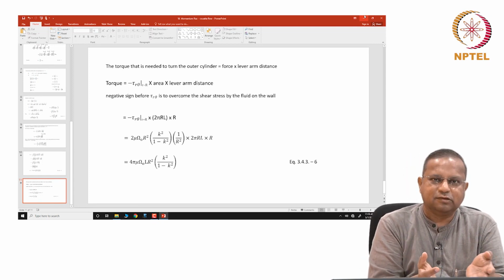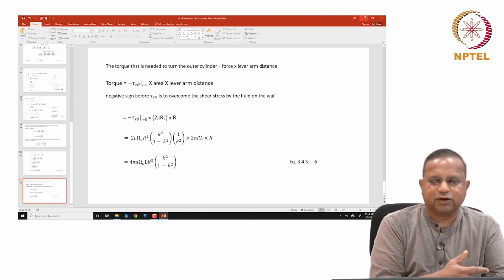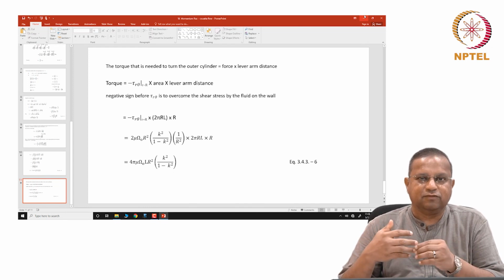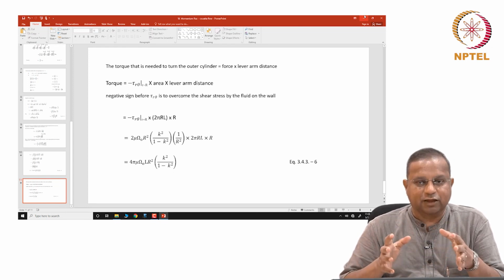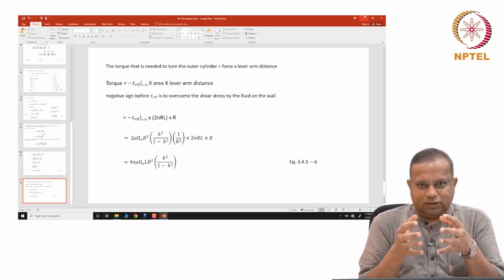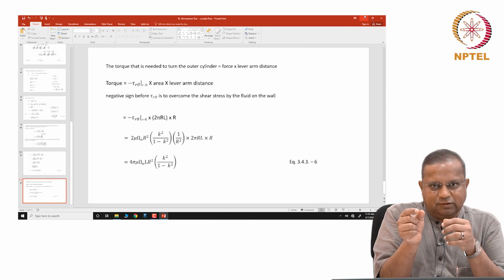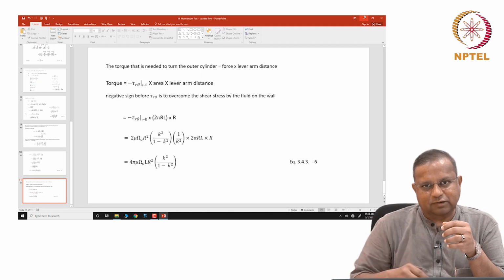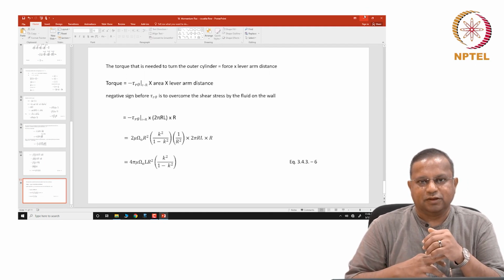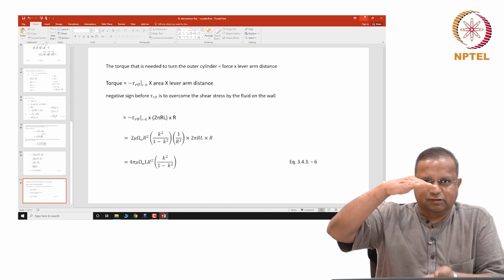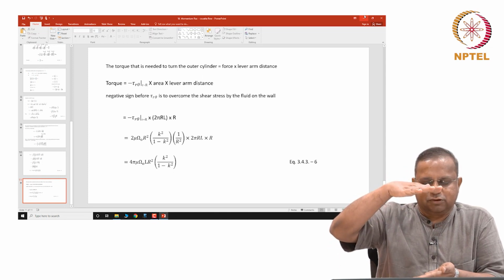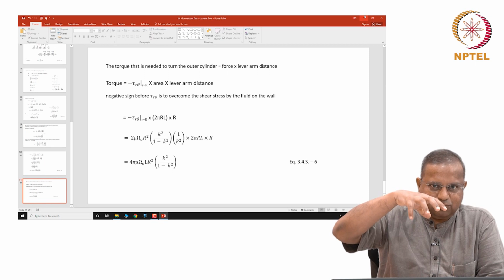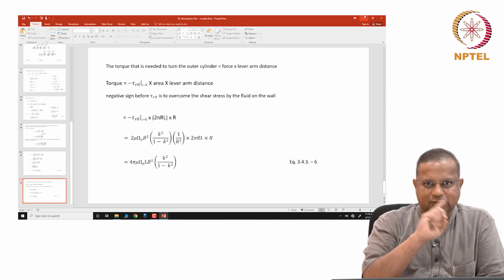We had to go through all this. Some of the expressions were available, some of the expressions we had to derive in order to design one such device. The device design was complex from a mechanical engineering point of view. You know, the space between those two steel cylinders is 2 mm. Okay, that is the annular space that we are looking at. And the outer cylinder rotates at 1500 rpm. Okay, huge rpm. And therefore it should not shake. It is about a foot plus in height, about 35 centimeters. So there cannot be any motion in any other direction except for this motion.